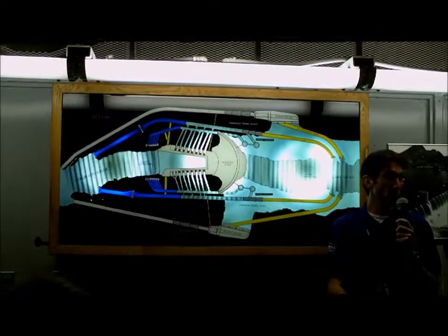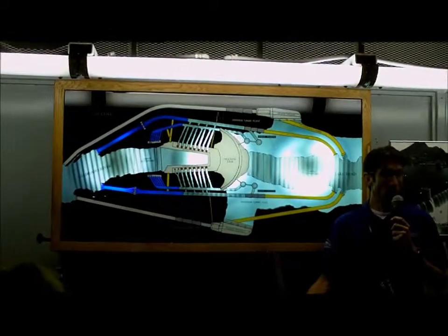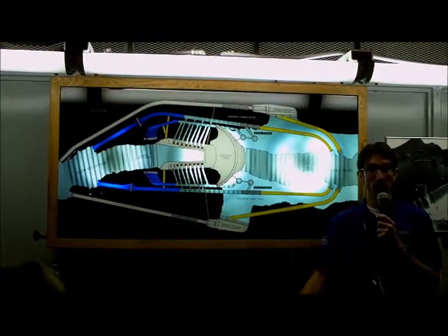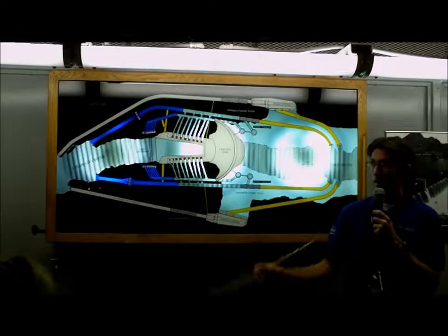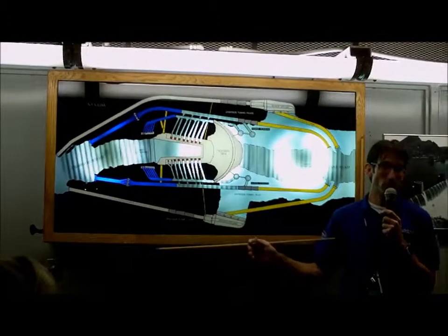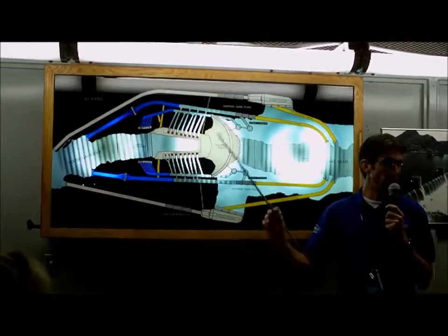So you can feel the vibration in the floor in this room right now as well. So that is the water moving through the penstock below us at that rate of 96,000 gallons per second. That rush you felt means they opened up another butterfly valve to put another generator online of the 8 that we'll be seeing up top.